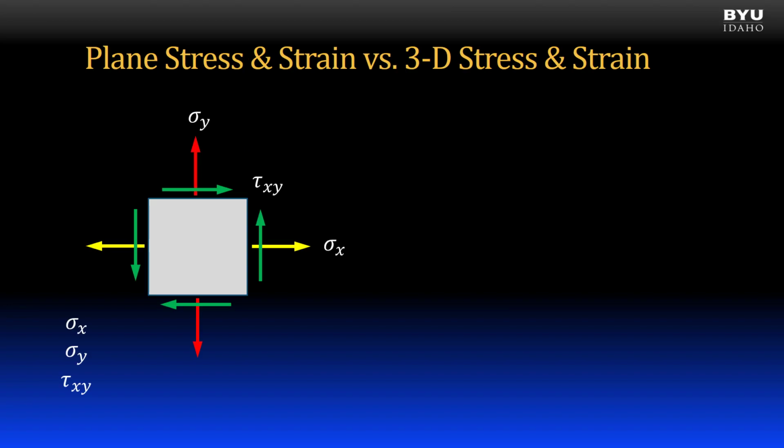The stress transformation we consider in this class is plane stress transformation. In plane stress transformation, all the stresses occurring at a point in a structure can be shown on a planar stress element, like the one shown. Note that there are only three possible stresses: two perpendicular normal stresses, shown here as x and y direction stresses, and a single shear stress, shown here as acting in the xy plane. Note that all stresses are in static equilibrium. For the shear stress, this means that all four sides of the element feel the same magnitude stress.